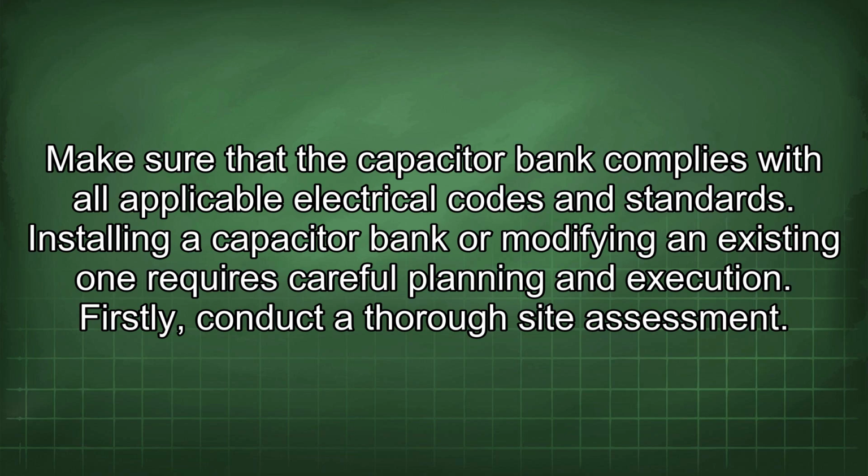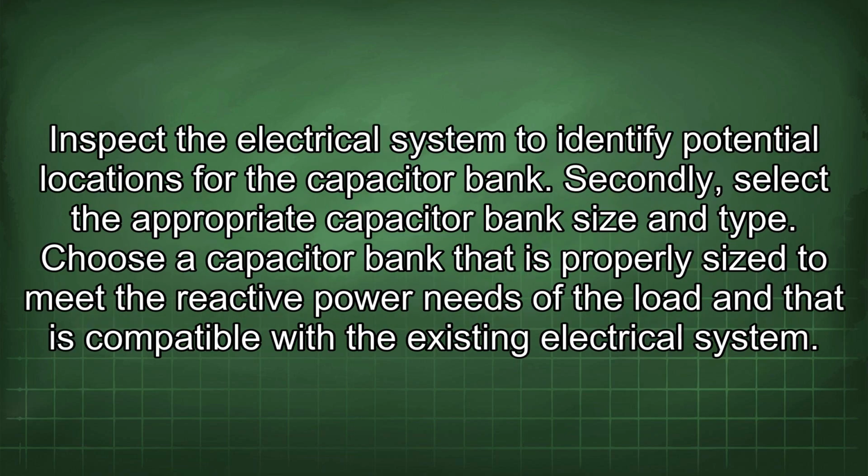Installing a capacitor bank or modifying an existing one requires careful planning and execution. Firstly, conduct a thorough site assessment. Inspect the electrical system to identify potential locations for the capacitor bank. Secondly, select the appropriate capacitor bank size and type. Choose a capacitor bank that is properly sized to meet the reactive power needs of the load and that is compatible with the existing electrical system.